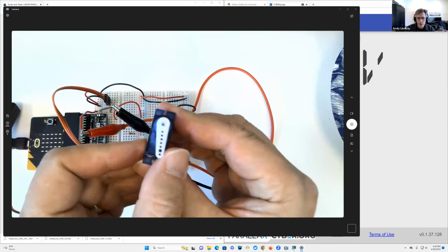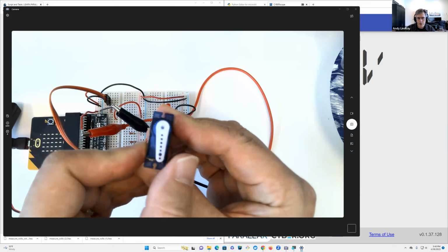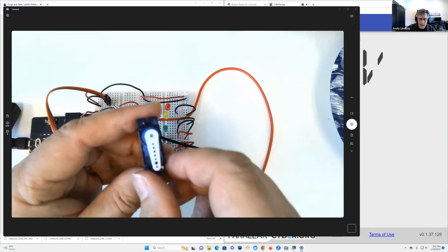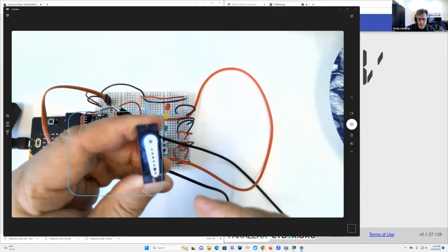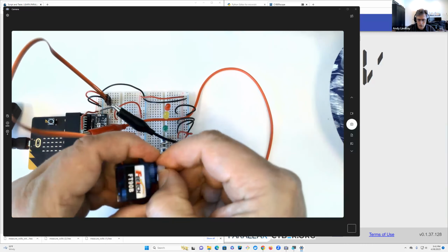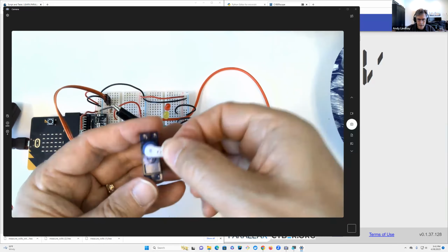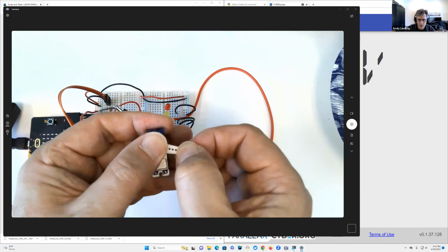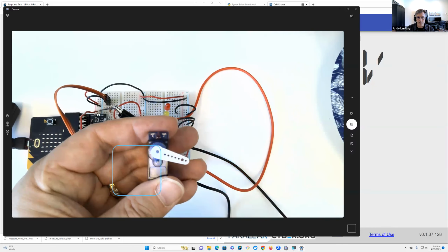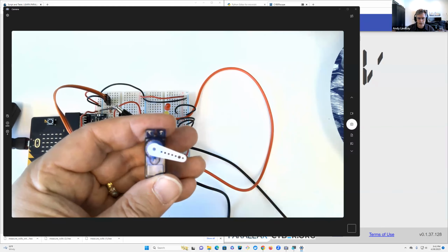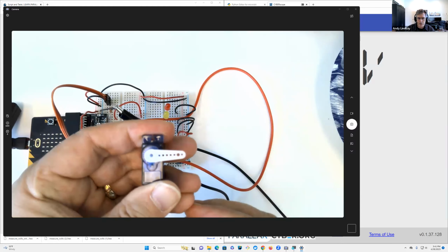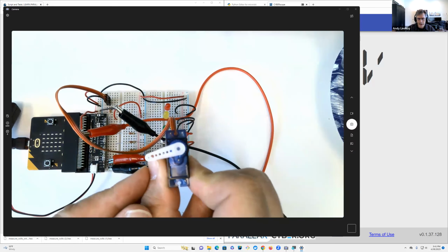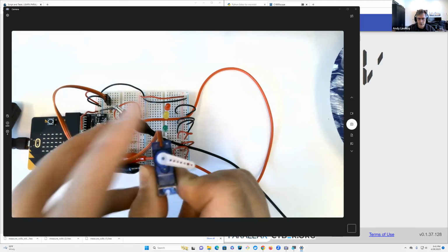Wherever you end up where you can feel the stopper inside the servo prevent you from turning it clockwise any more, just leave it there. And once you've got the servo turned all the way to its clockwise limit, then you can take the horn back off and put it just a little bit low, pointing straight to the right. So maybe just a couple degrees below, straight to the right. That's probably about the natural clockwise limit of the servo if you're going to use it to point to 0 degrees like that. And then you can also bring it around, and you want to see it pointing downward at about the same angle at its counterclockwise limit as you do at its clockwise limit.